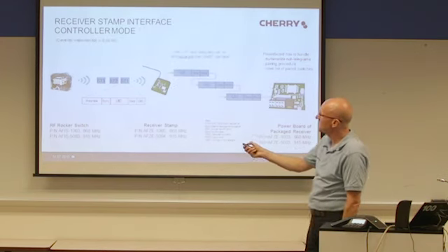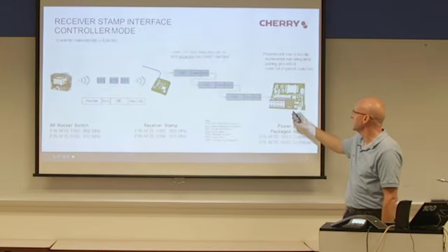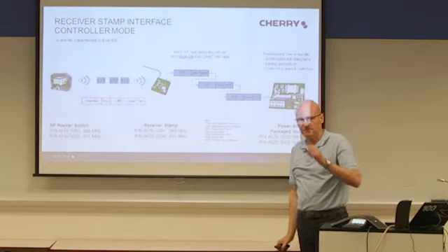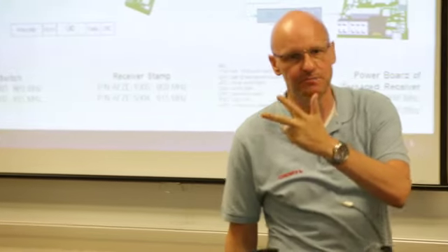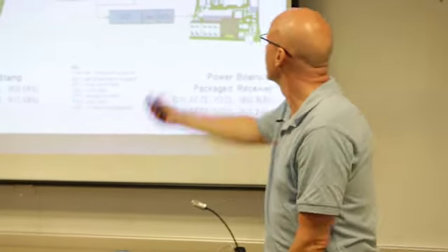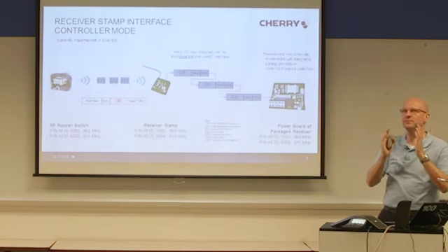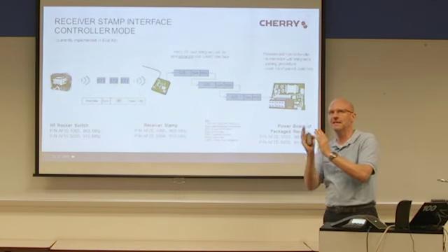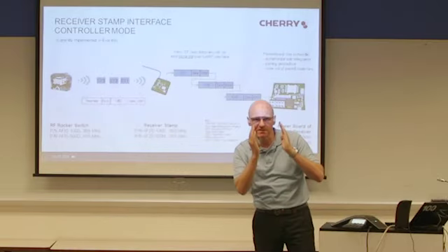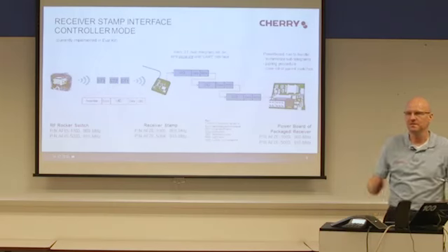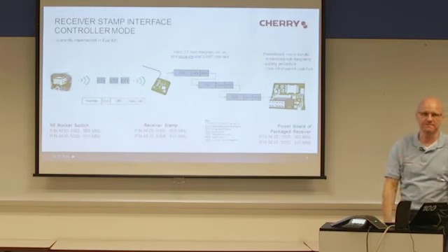Remember, in the first step, the power board gets the information: switch 17 is pressed, switch 17 is pressed, switch 17 is pressed. And the power board has to handle, okay, these are 3 subtelegrams because the time between the telegrams is very short. It's from the same unique ID and it's the same release date. This must be 3 subtelegrams.